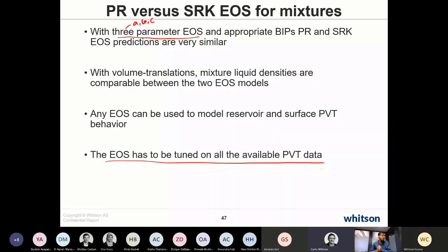You use this model that's matched and tuned to vapor-liquid equilibria data. That's a basis model that's used together with other models to do the wax and asphaltene type predictions. So it's an add-on. I don't have to rebuild everything. No, exactly. The preferred models for solids modeling have the cubic EOS as the starting point.